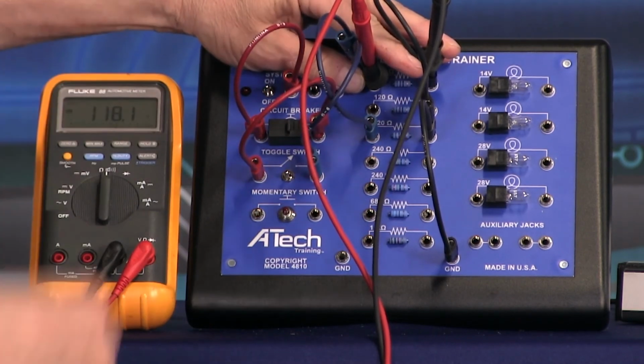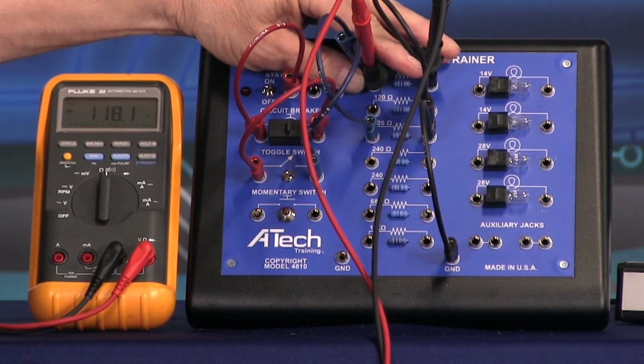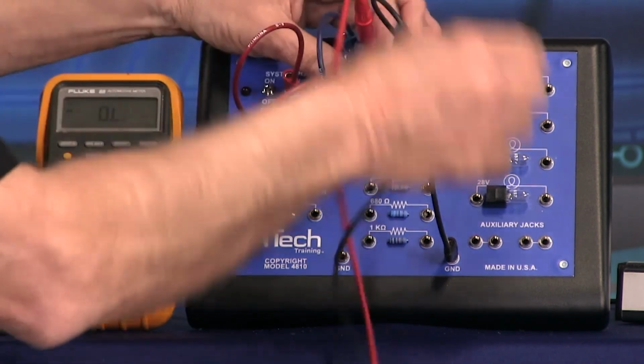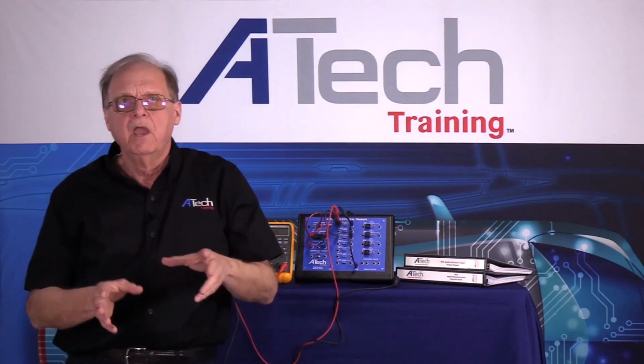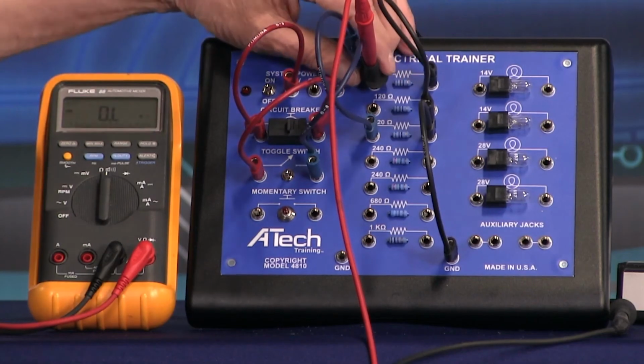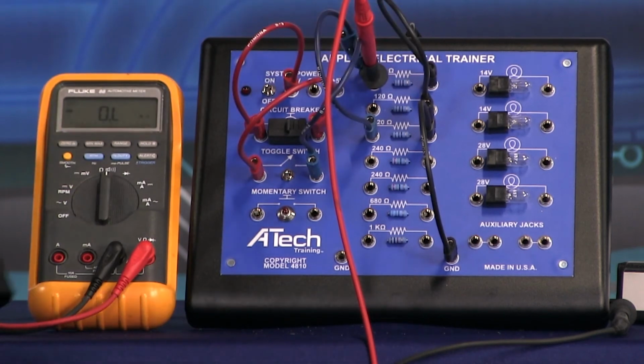Well, I have 120 as a resistor. There's a little minor variation in resistors, 2% difference. So that's a proper way to test it. So again, if I'm in a circuit and I'm checking resistance, I need to remove one lead. And that's why there's an emphasis on the testing. When you go through the testing procedure in the manual, it actually tells you that you need to disconnect each component as they go through.